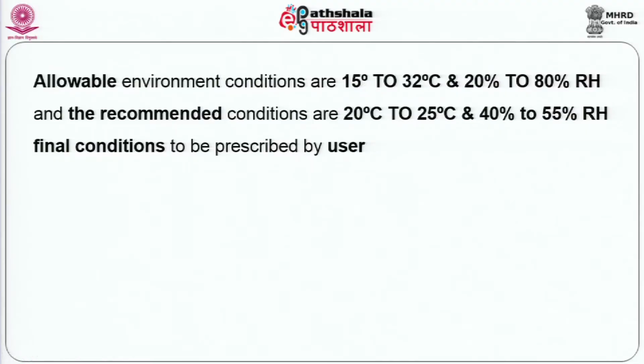18 degrees centigrade was perhaps the high point. They wanted temperatures even lower. That was when the market was entirely taken by IBM computers, ICL computers. Later on, slowly, as components started getting tropicalized, as components started coming from all over the world, people realized that there was too much of an impact on air conditioning, and today the computers are rated for average conditions like this. That means the temperature, they say, can be 15 to 32, which means you can use it in a high latitude area and somewhere in the tropics with comfort air conditioning.